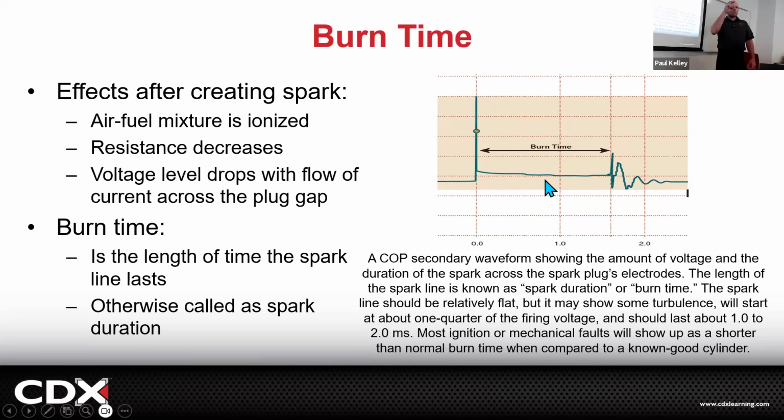So the spark to you is just a boom and it's over. But in reality, the spark starts and it keeps on arcing until it doesn't need to anymore and all the combustion should be complete, right? So the burn time is right here. This is the actual burn time. Sometimes we'll call it spark duration too. We need a certain amount of burn time to completely consume all that air and fuel. We need to burn it all up. If we have a short burn time and we leave air and fuel in the cylinder, why is that bad?